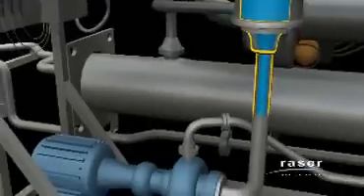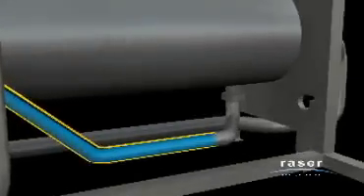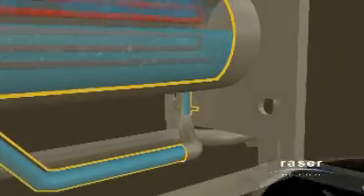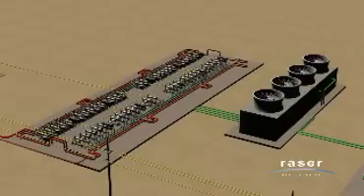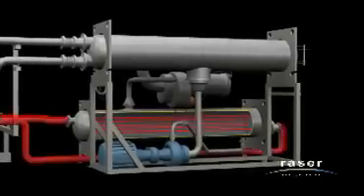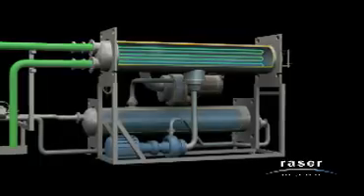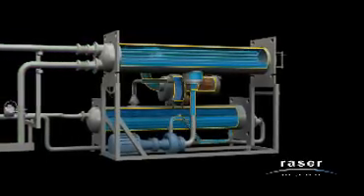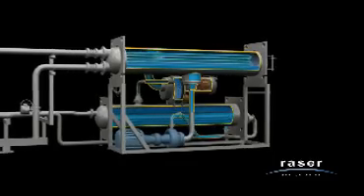The working fluid now flows down the tank outlet to the pump, where it is repressurized and injected back into the heat exchange tank to repeat the process. In order to be used again, the cooling water is returned to the cooling towers where it is cooled back down to 67 degrees. It is important to note that the three fluid systems of hot well water, cooling water from the cooling tower, and system working fluid remain in their own separate loops and never mix, so there is no contamination and no emissions.